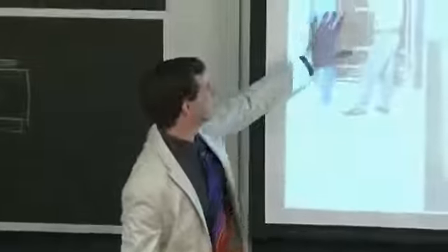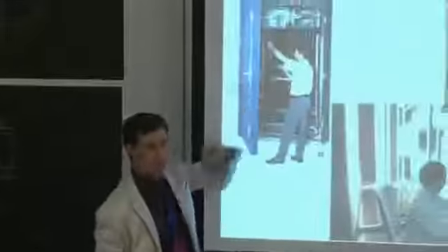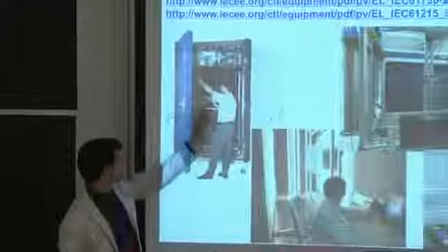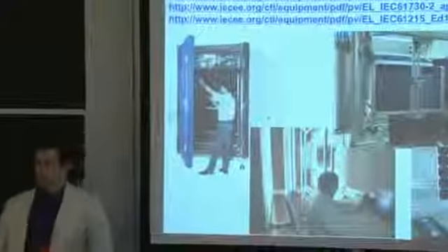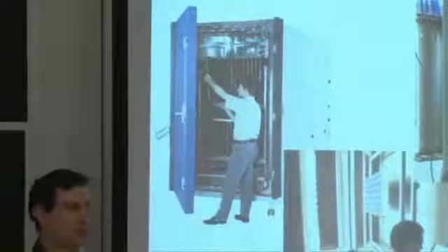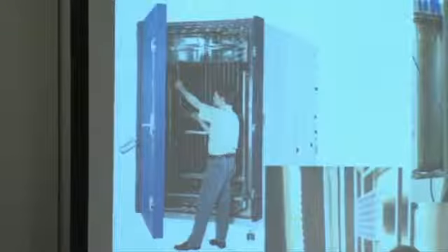Included in the test is environmental cycling, where you take a module, stick it inside of what looks like an oven, and it heats it up, cools it down, heats it up, cools it down, or maintains a high temperature with high humidity. Different types of environmental chambers do different things, but they're meant to simulate an accelerated aging process. Again, since most diffusion processes are driven by Boltzmann statistics, there's an exponential increase with increasing temperature, and hence we can simulate accelerated degradation at higher temperatures.